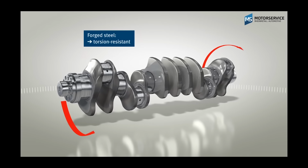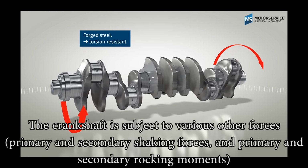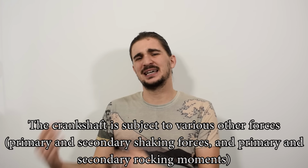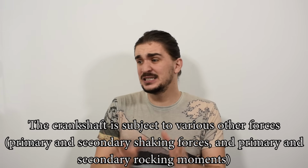infinite number of these extremely strong punches before it comes to the end of its lifespan. And combustion pressure generated forces are just one part of the forces acting onto the crankshaft. It also experiences primary and secondary shaking forces and primary and secondary rocking moments and a bunch of other stuff. So it really is going through hell all of the time. And this is why it's absolutely imperative that the design and the manufacturing process of a crankshaft is really good so that a crankshaft can survive all of this hell for a very long time.